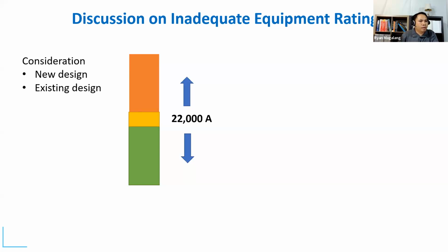So the manufacturers would publish tables for which X/R ratio they have tested the devices for. Like I said, and then you'll have to compare that.